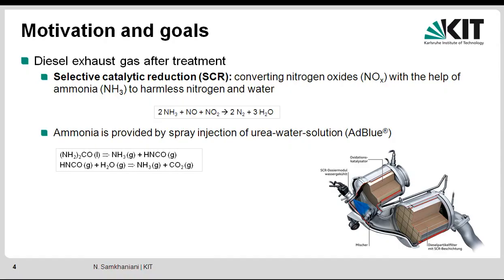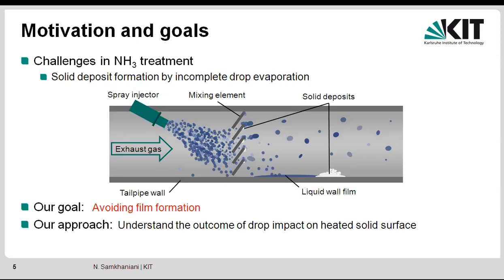The motivation for this study was in a diesel exhaust gas after-treatment system, where AdBlue is injected into the exhaust gas to convert the NOx into ammonia and water. We know when the AdBlue is injected, a liquid film forms on the wall. The evaporation of this film creates some solid deposit, which impairs the performance of this system.